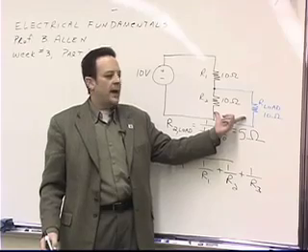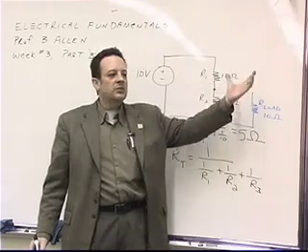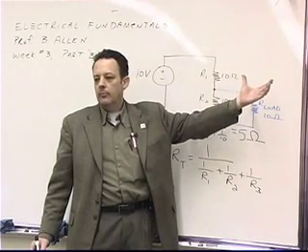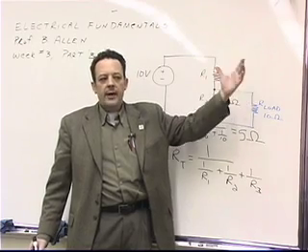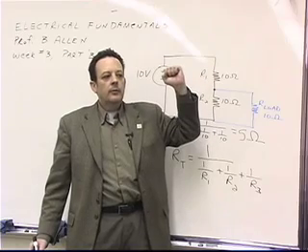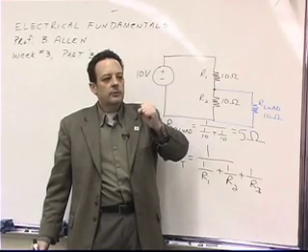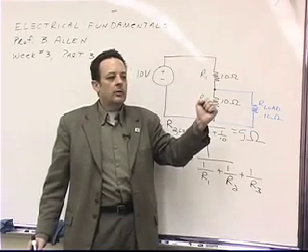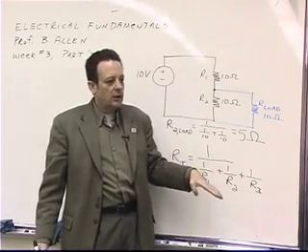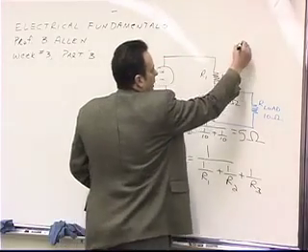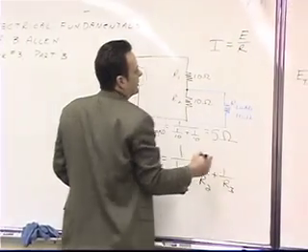Resistors that are connected back to back or in parallel give you a smaller resistance when you total it up. That's why they draw more current. That's why when you plug in 4 hair dryers instead of 2, you get twice the current. Because the resistance has gone down, and current is equal to voltage divided by resistance.